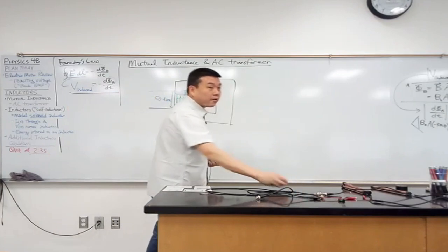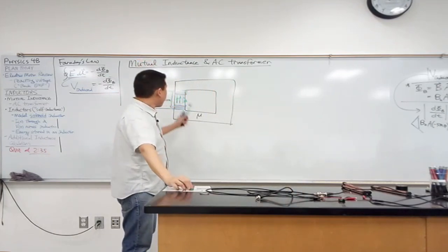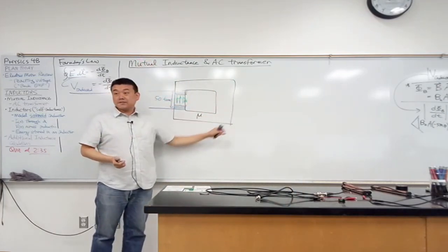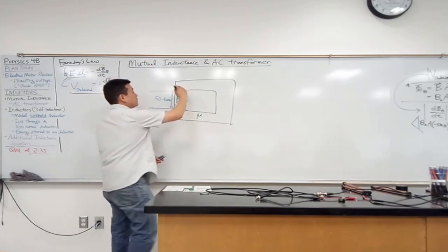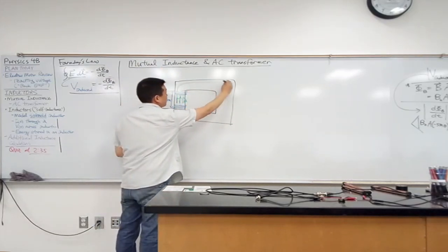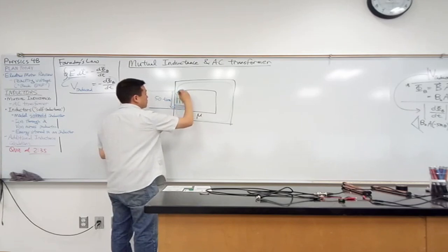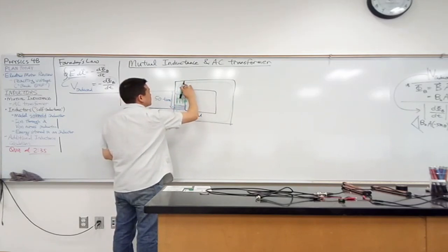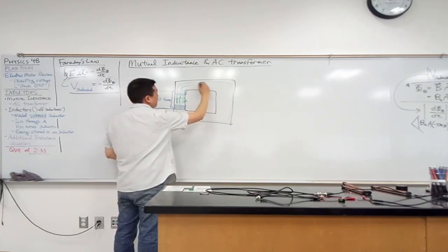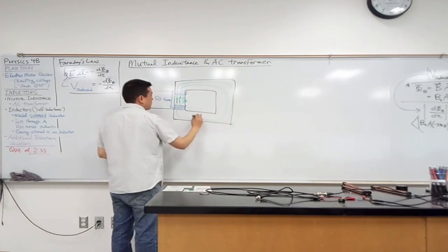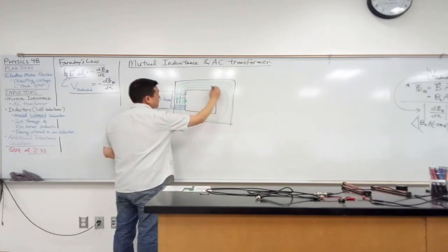But when you have a ferrite core like this, these field lines get trapped inside. So they don't actually go out anywhere. The field lines will just bend around the material and close on itself like this. So in some sense, it makes your transformer more efficient because you're not losing any of these field lines that you generated by sending current.